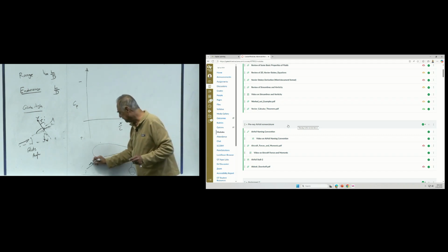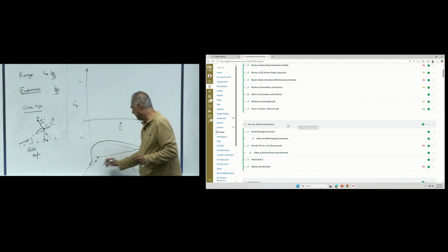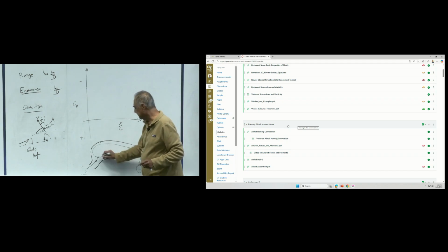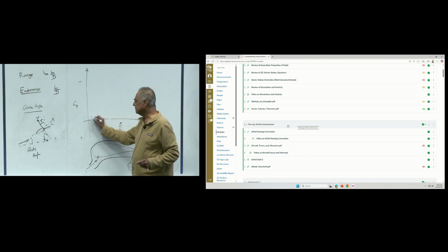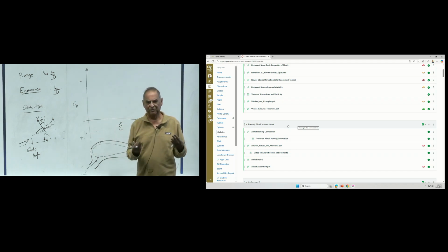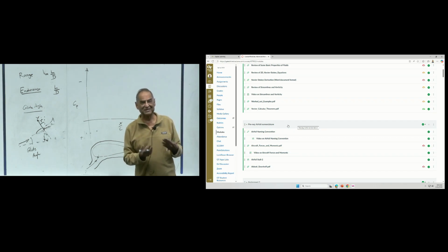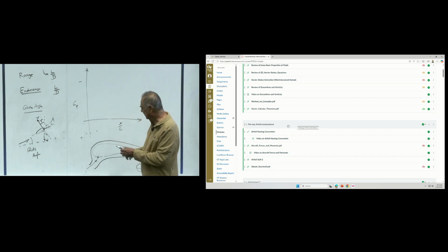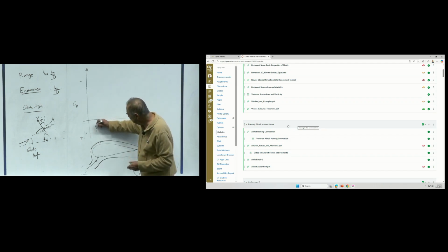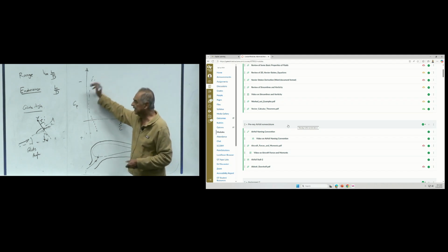And then the flow goes over the upper surface, then the flow goes to the lower surface. Right at the stagnation point, you'll have the highest CP value, close to 1.0 or so. One is a theoretical maximum for incompressible flow. Then as the flow goes over the upper surface, the pressure will start decreasing, so Cp will even become negative.